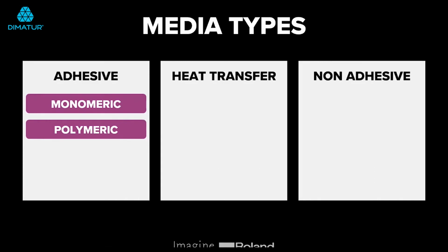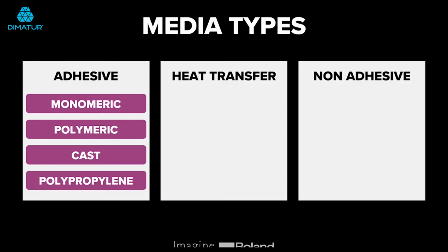Finally, the third type of vinyl that you'll come across quite often is a cast vinyl. So a cast vinyl is made, rather than starting with a block and kind of rolling it down, a cast vinyl is poured instead. So it's made at its end output size, meaning that it's most flexible and it's best designed for working with things like wrapping vehicles, or sometimes, for example, we have people on courses that will wrap kitchens. That type of material is great for that. In terms of pricing, you'll see a difference between monomeric, polymeric, and cast will tend to be the most expensive of those.